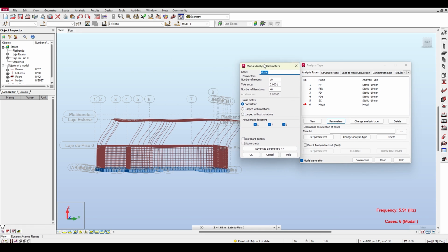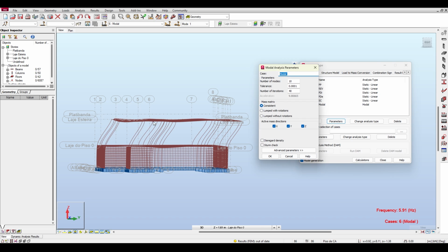Now, why is this the answer you will find? It's because we have just explained it. The mass that is vibrating here is only 50% of the structure. Why? Because the lower part is much, much stiffer, which means we need higher modes, because stiff equals more frequency equals higher modes. So let me try something here.